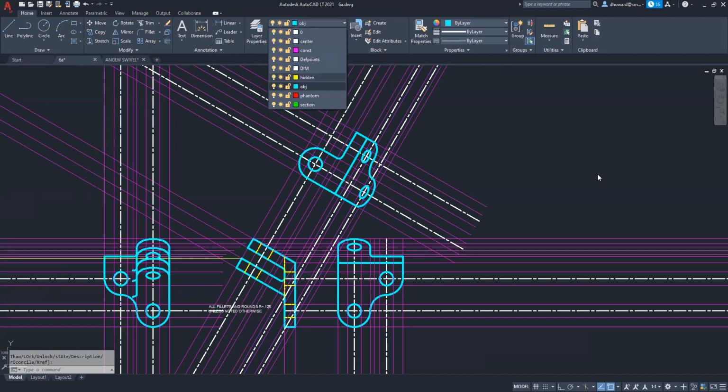It's the line of sight. So to see something true size, you need to look at it perpendicular. So these construction lines, basically, they represent our line of sight. We are looking at this face perpendicular to this face. It appears true size. We are looking at this other face at a sharp angle. So it appears foreshortened.